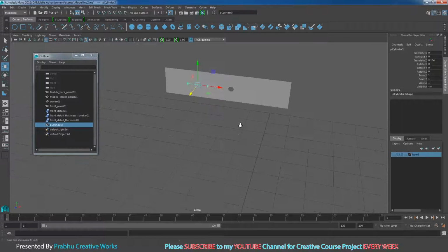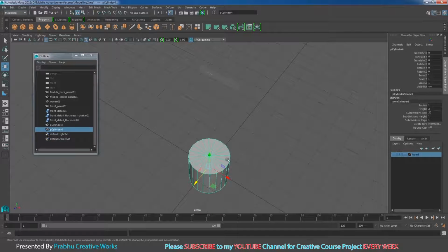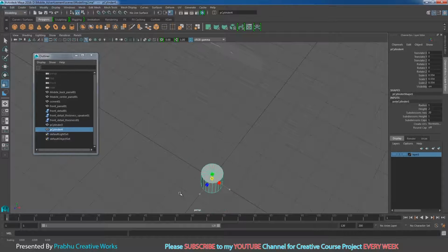So now we want to make a cylinder over here. So click on polygon cylinder. It will automatically be created in the center of the grid. So press R and scale like this. So press E and rotate X by 90.